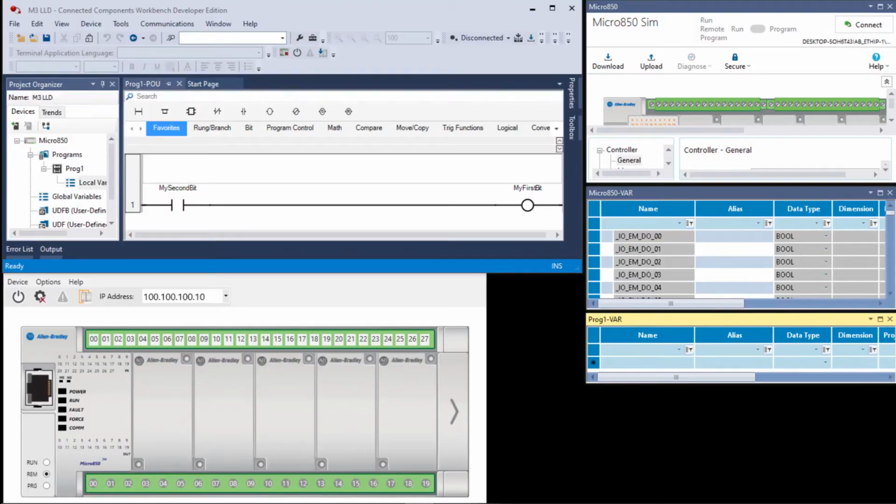So far, we introduced you to the simulator, and you see it's been turned on. It's not powered up, but it's turned on in the sense that it's been created in memory. We also discussed the relationship between the memory locations that represent the state of input screw terminals and the state of bits of memory that will be converted to the screw states of output screw terminals. We created a rung of logic. We demonstrated the difference between what you see in the run mode and program mode, online and offline.